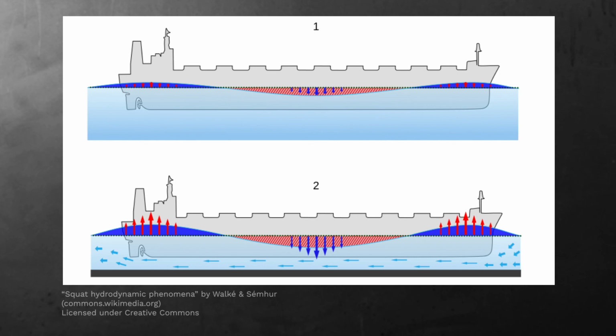In the lower slide, we see the same ship going through a canal. And because the ship itself is displacing a lot of the water, it accelerates the fluid, which magnifies the waves, which also magnifies the changes in hydrostatic loads that the ship has to resist.